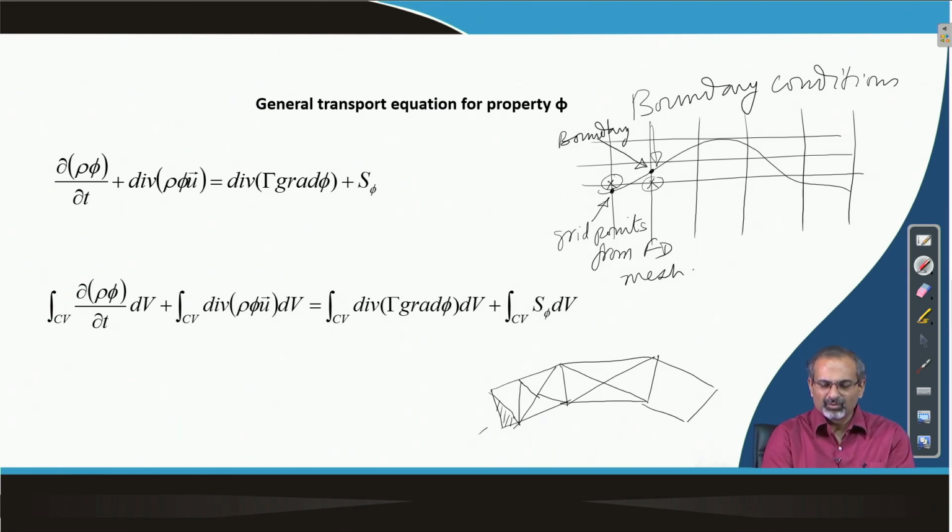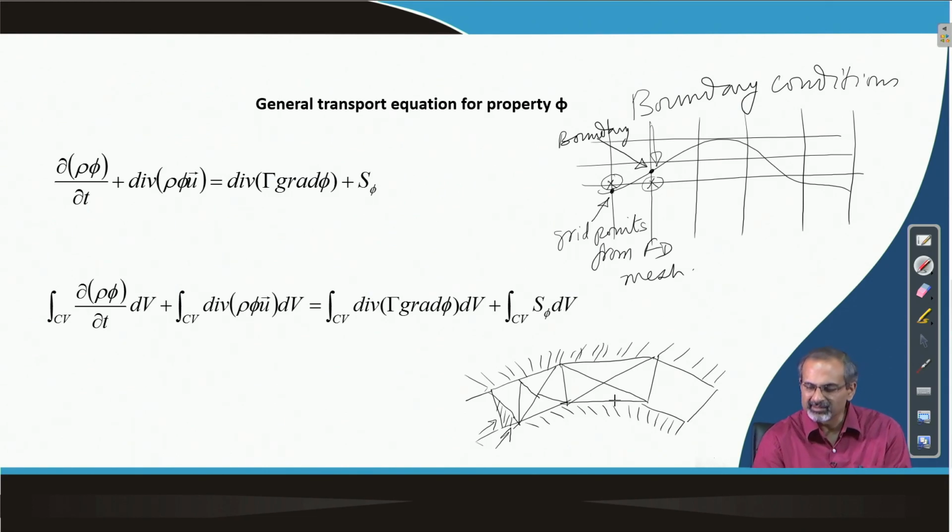it may allow, for example, mass flux into itself from this direction, and if this is bounded by some solid surface. So, if this is part of a solid surface at the bottom and this part on top, and you have discretized the intermediate domain by using these cells, then whatever enters this cell from these two faces is bound to go out through this remaining face.